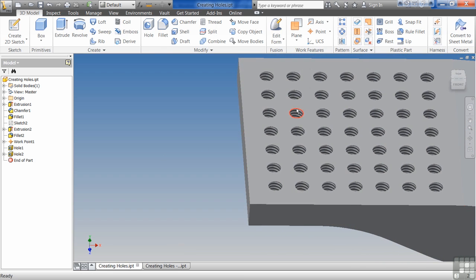Now the threads are not threads. They are just bitmap references. Even then, that's kind of excessive. If you've got a great big giant 10,000 part machine, it's really not necessary to put the threads in there. You can just put the holes in there, whatever size you want them to be. The threads are not real threads. I can't zoom in and see the pitches of the thread.